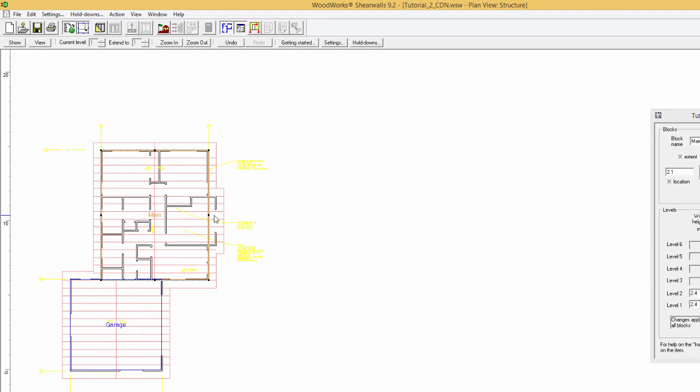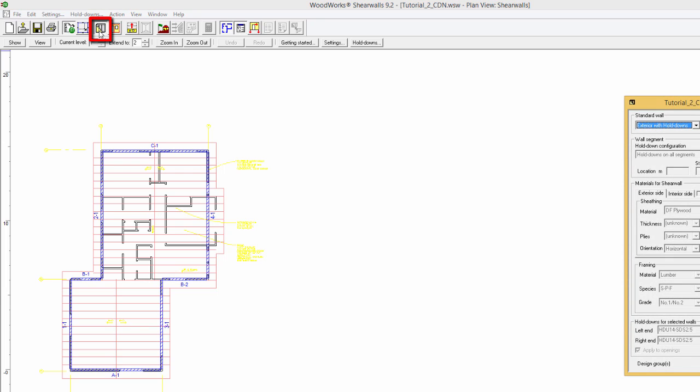Now we will insert the walls. Upon exiting the structure action, walls are placed automatically around the edges of the intersecting blocks. It will not be possible to move, resize, or reposition the blocks while in walls action, but the blocks will automatically resize to follow movement of the exterior walls.